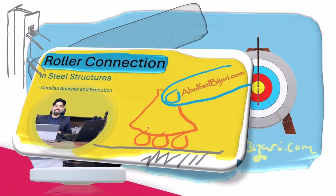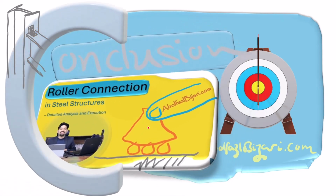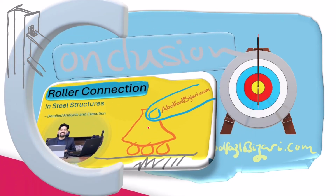Summary. Pin support is one of the most commonly used supports in structural engineering because it resists horizontal and vertical forces but not bending moments. And in real construction, it is created using angles and a gap for free rotation. It is used in bridges, building frames, and steel structures.